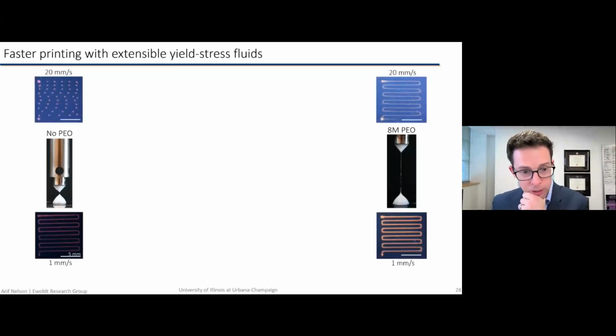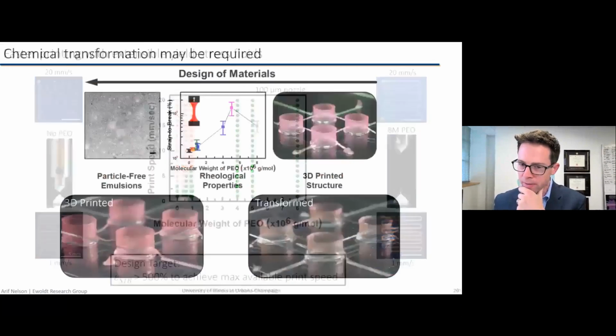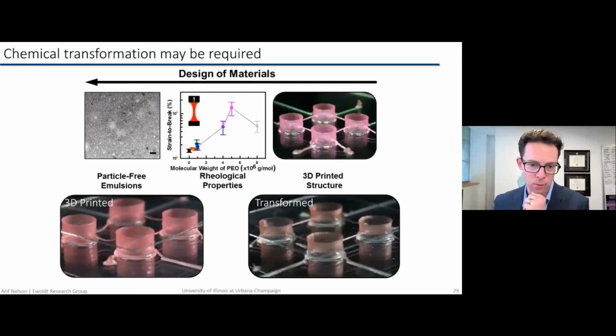Oh, great question. To the extent that we've looked, we haven't been upset with any residual changes in the dimensions, but dimensional consistency certainly is an issue with any manufacturing process. This happens to be a 2-step process. It requires both a chemical and a thermal annealing step. Essentially, the chemists suggest that there's some remnant material that allows the silicone oil to cross-link, to initiate a cross-linking reaction.